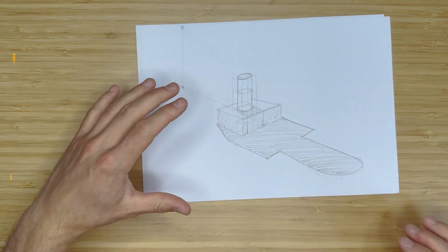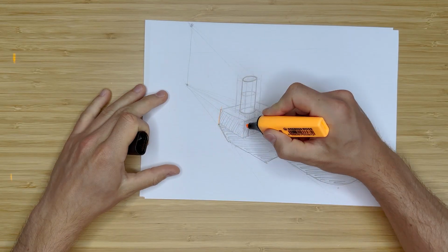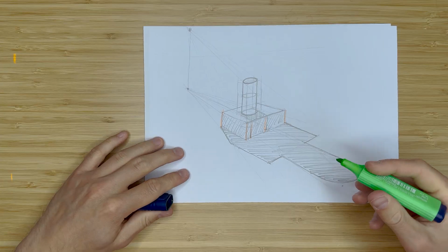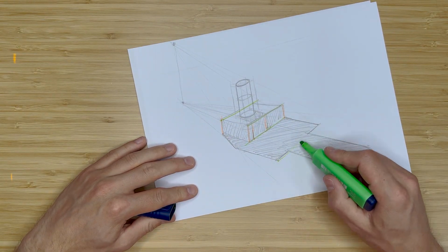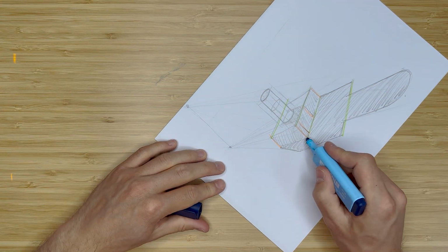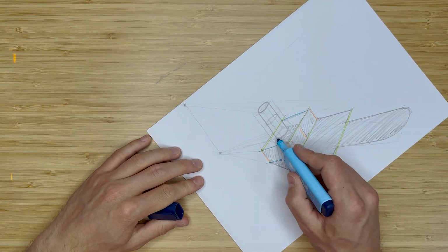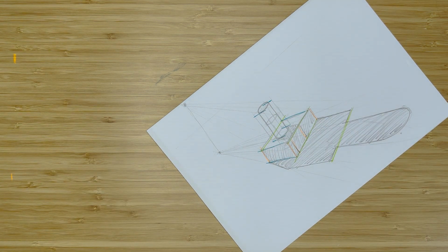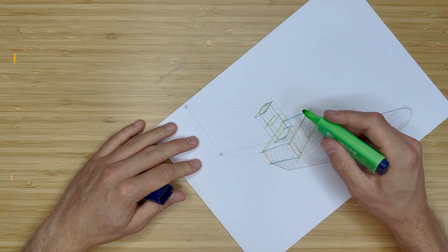Have a play around, work out where your light needs to be, work out where your source is. Same as always though, going back to the key concept, make sure any vertical lines are vertical in your initial area, make sure any of your vanishing point lines here are going off in that direction. This should also meet it because of how the perspective is. And with your blue lines, keep them going off in the right direction to your vanishing point on the left. With the way I built this part on here, it's exactly the same thing. Those lines will be going off and my green lines will be going off to the right. And that's how we got our major and minor axes.